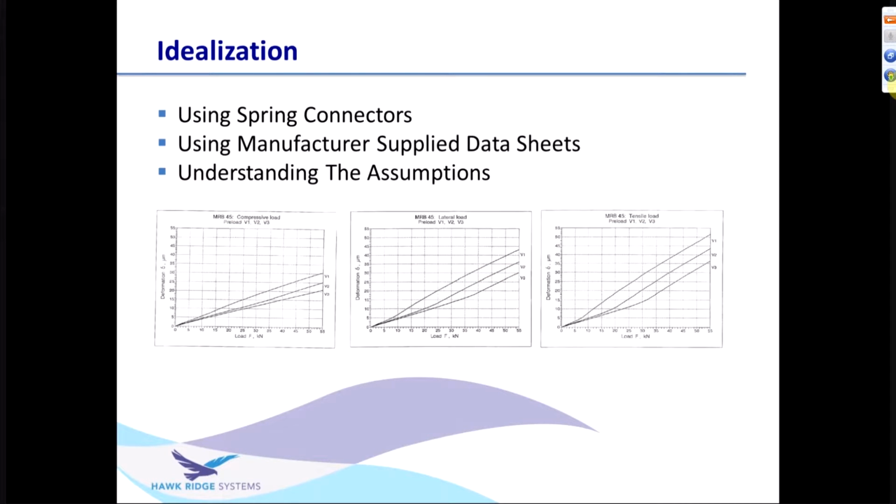So as I mentioned in the planning portion of the study, we decided to use spring connectors along with the simplified geometry in order to account for the stiffness of the linear rails and ball screws. This would provide us with a good balance between accuracy in our results and solve time. What Ingersoll provided us with were data sheets from the manufacturer for these assemblies, which we would then use to define the stiffness for the spring connectors that we wanted to include as well.